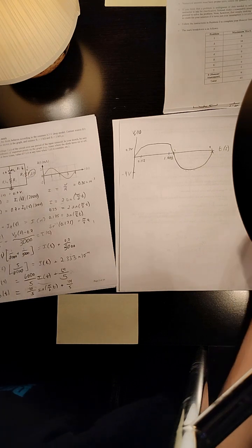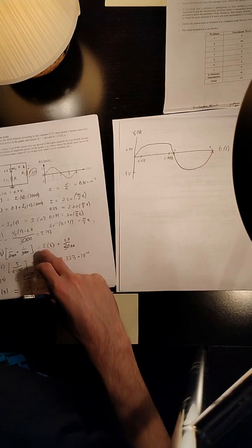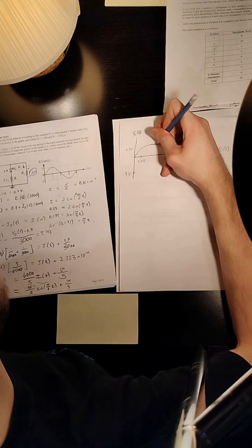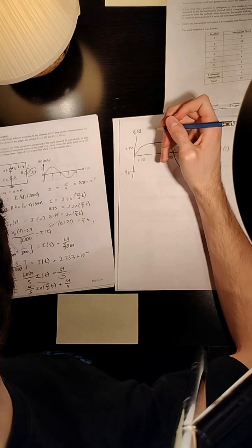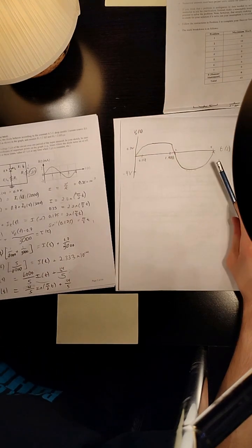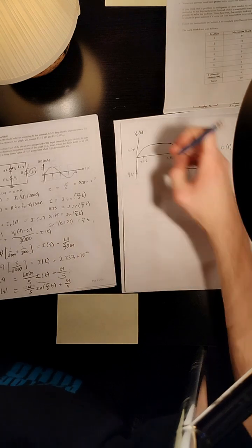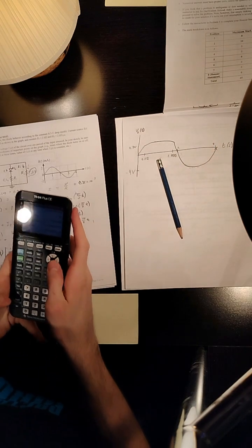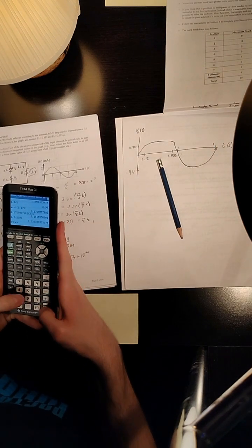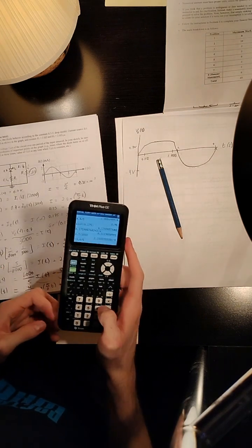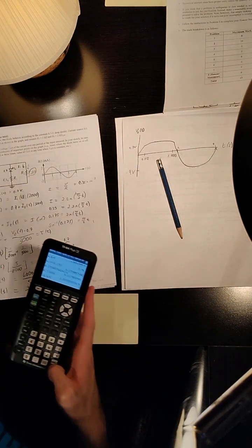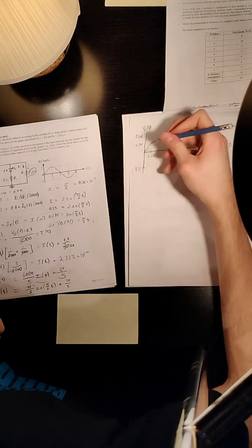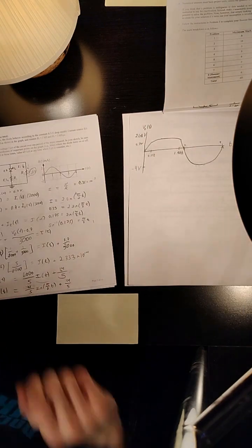All right, let me continue. So that is the problem, and then we can put in the maximum here. That would be 12 over 5 plus 1.4 over 5, so 13.4 over 5 volts. 13.4 divided by 5 is 2.68 volts, which, according to this diode model anyway, would be our maximum voltage.